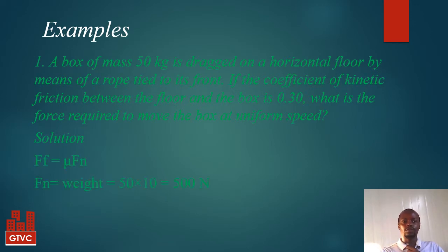The solution will be guided by the formula for calculating the coefficient of friction, so that we make the force required to drag the box the subject of the formula. We convert the weight from kilograms to Newton, then we multiply the coefficient of friction with the force or the weight of that particular box. We end up getting 150 Newton.